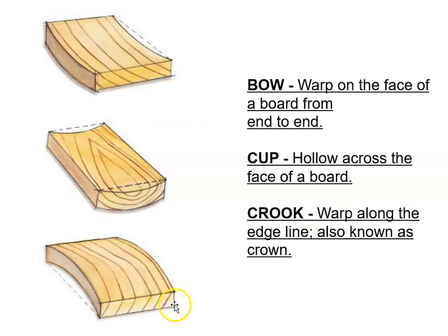And when carpenters make walls, so we're talking about dimensional lumber framing, when they're putting up walls or putting together built up beams, for instance, a girder, and doing this all out of 2x material, they will look down at a piece of wood, they'll sight it, they call it, and they'll see which direction the crooks are running.